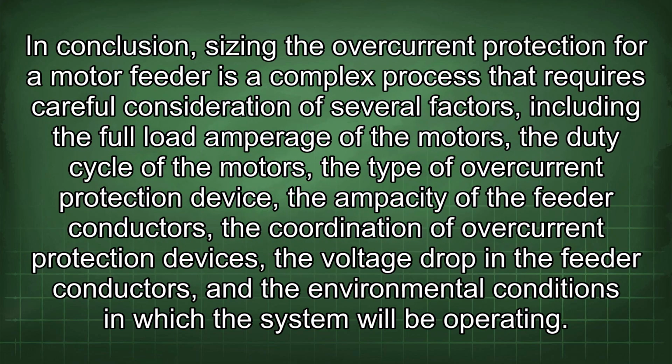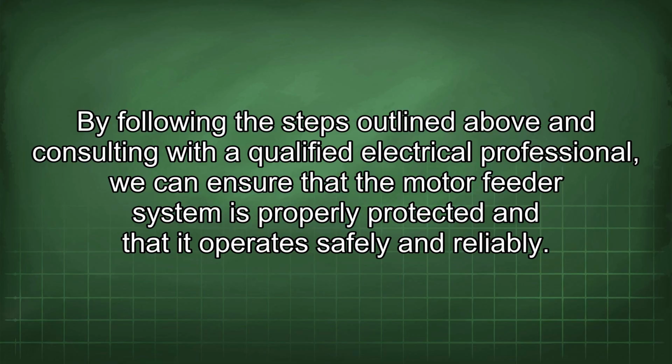In conclusion, sizing the overcurrent protection for a motor feeder is a complex process that requires careful consideration of several factors, including the full load amperage of the motors, the duty cycle of the motors, the type of overcurrent protection device, the ampacity of the feeder conductors, the coordination of overcurrent protection devices, the voltage drop in the feeder conductors, and the environmental conditions in which the system will be operating. By following the steps outlined above and consulting with a qualified electrical professional, we can ensure that the motor feeder system is properly protected and that it operates safely and reliably.